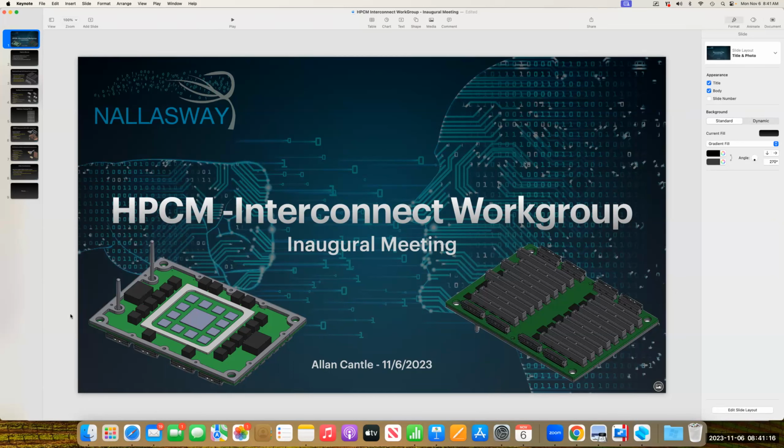millimeters, which would be the ideal substrate thickness. Now, by the way, on that topic, you're seeing these packages become huge, and so we're beginning to ask the question: why don't we make these modules also absorb power components like the capacitors into the package? Then they have these horrible solder balls for signal integrity, and so we lose 2 to 5 dB just coming out of the package.